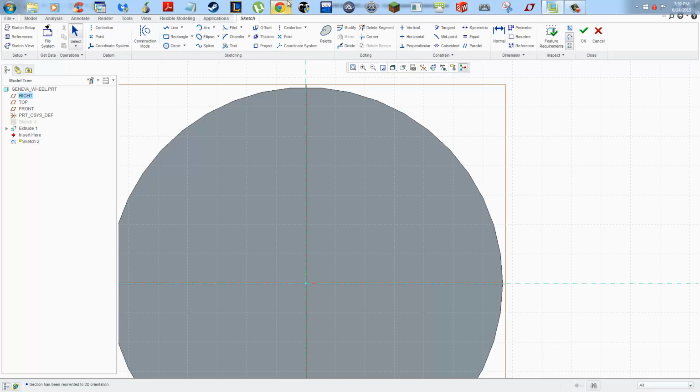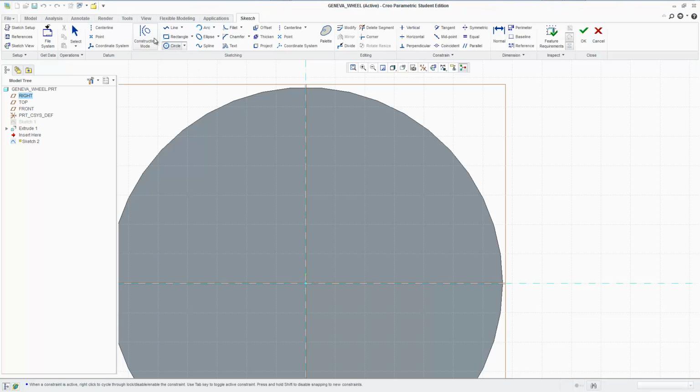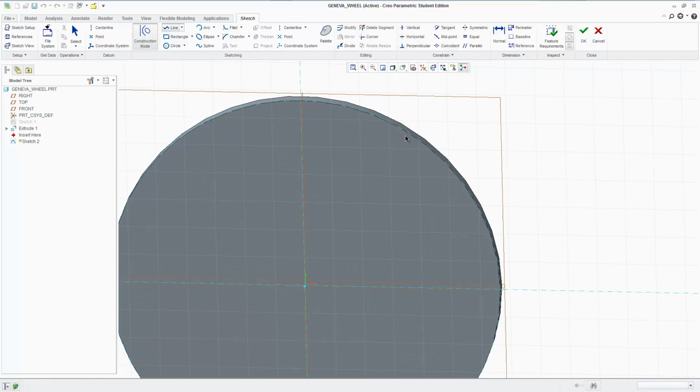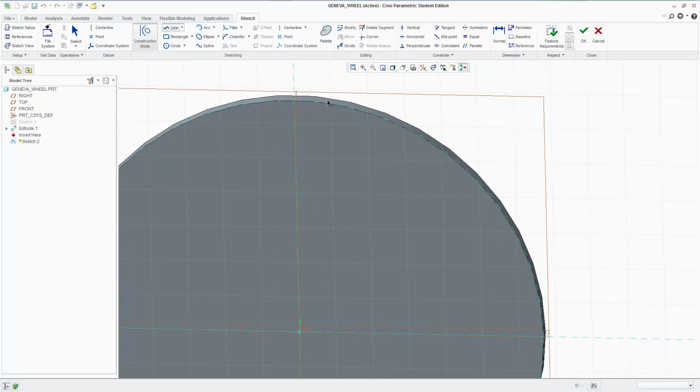And let's see, the distance for that is, first I'm going to go into construction mode and get a point where I can start. So let's see, actually, I think I was going to save this for the advanced stuff, but okay. So I want to make a circle, or make anything on a piece of geometry that already exists. There's a way to do that where you can make references, and you can have these blue dotted lines as references.